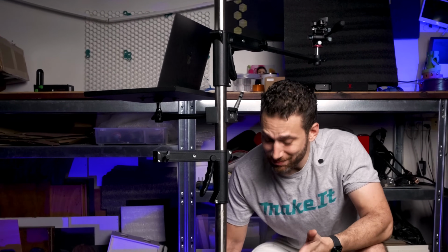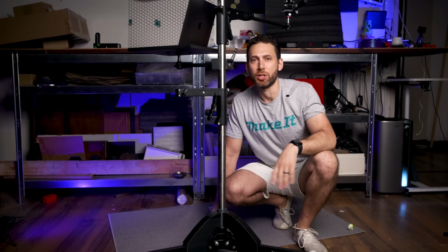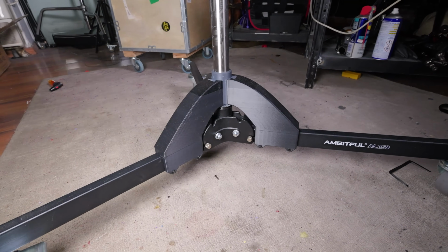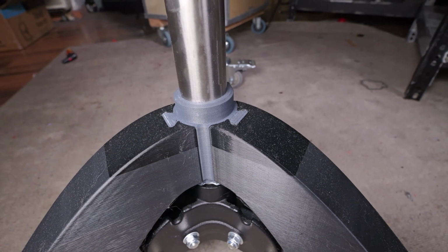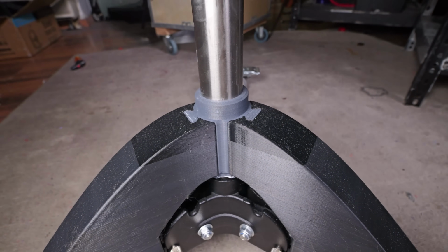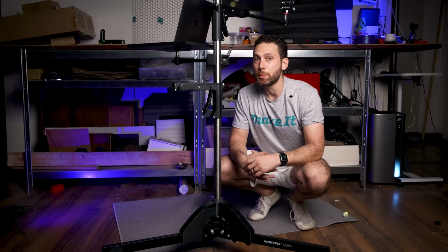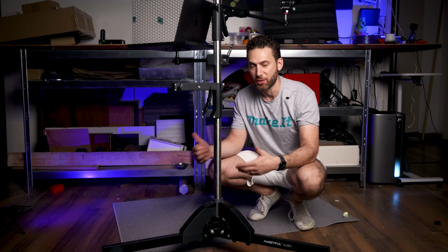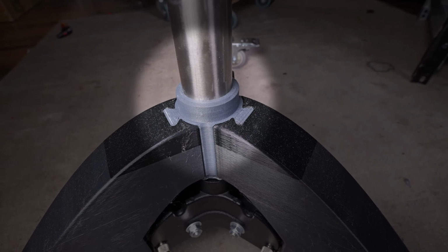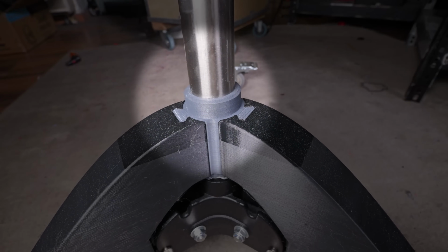Now, design-wise, this really wasn't too difficult, but there was one unique challenge that I do want to point out for your edification. This design mixes 3D printed parts and metal parts, which meet up in various different points throughout the design, including on the smooth pole, the legs, and the metal hardware. So this meant that I needed to be mindful of what size tolerances I was using and modeling at different points in the print. Actually, I had too tight of a tolerance on the main center bore, which meant that I needed to sand it down.